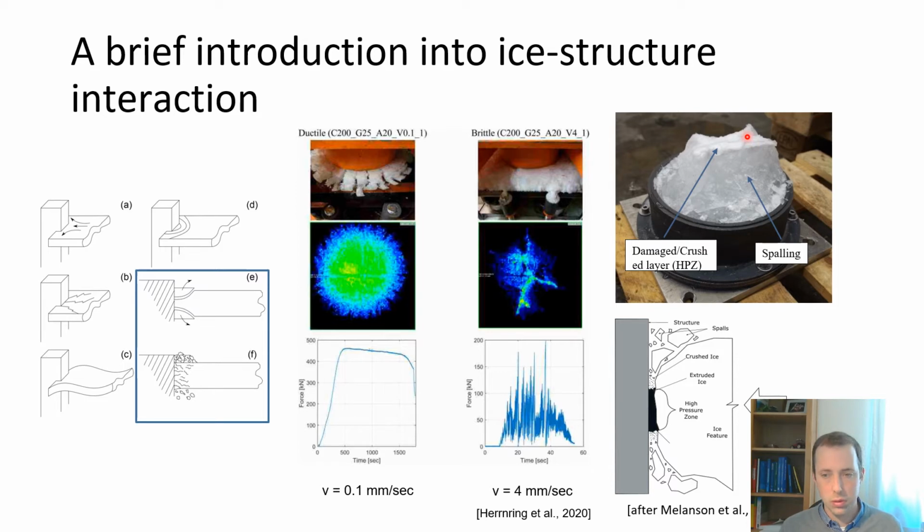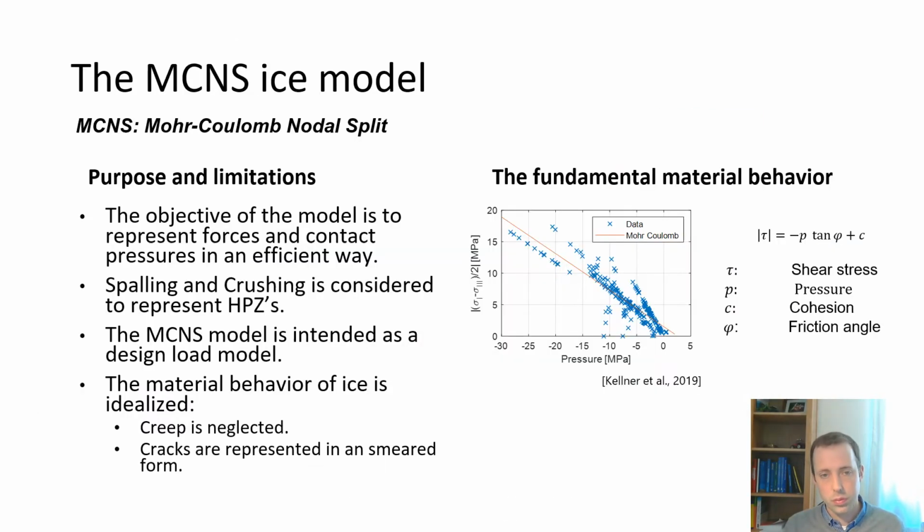This means that ice structure interaction is always, also in brittle mode, limited by spalling, so fracture mechanics, and also the continuum mechanics problem, a dynamic mechanics problem here in the crushed layer. And those processes are very important for the ice loads.